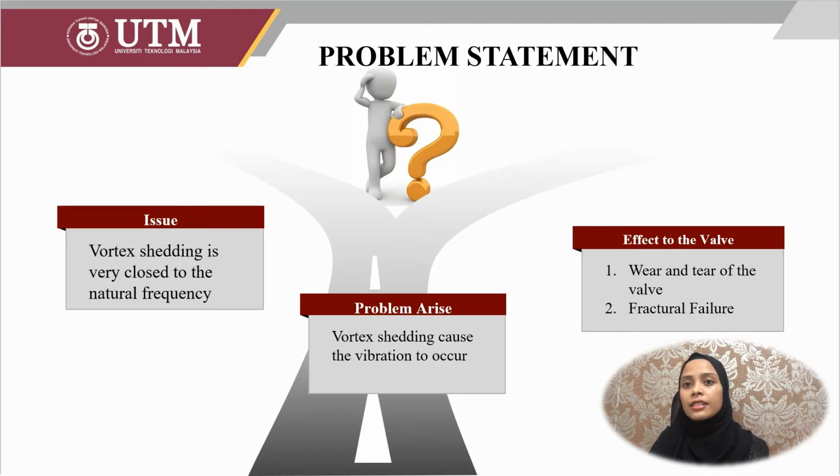Excessive vibration can result in wear and tear of the valve, or in the worst case, it can cause fracture failure. The next video is an example of when the vortex shedding or the structural frequency is very close to the natural frequency.